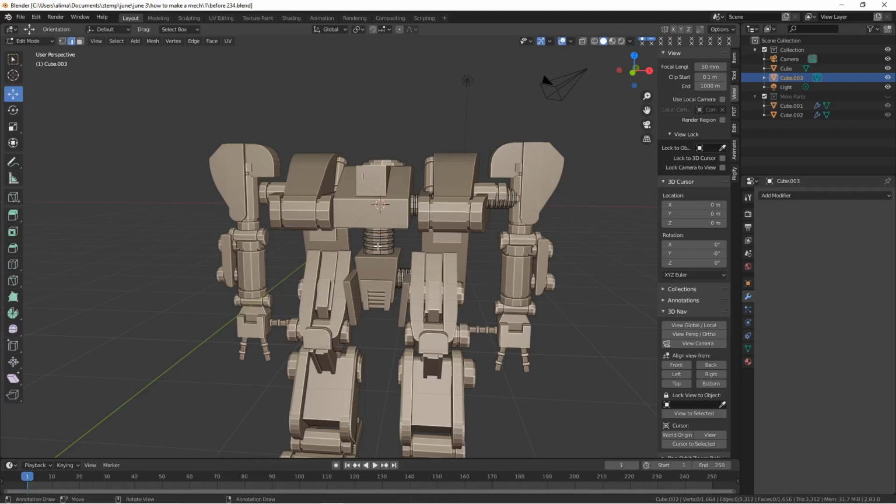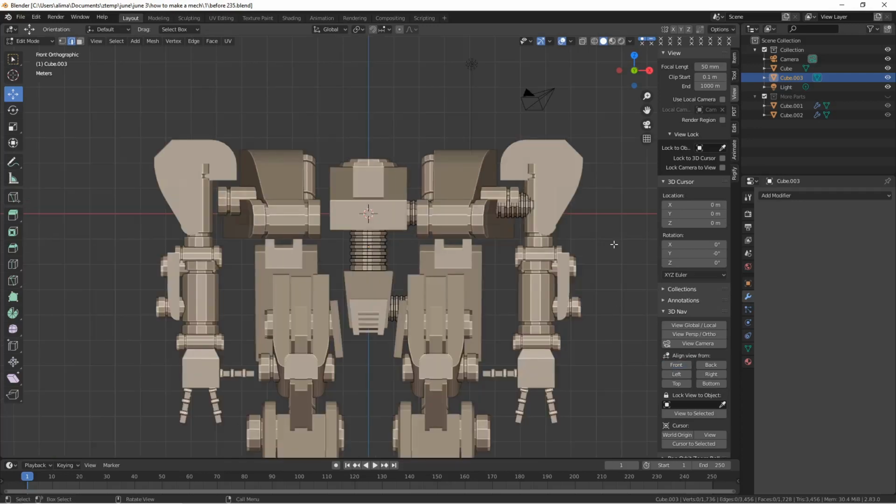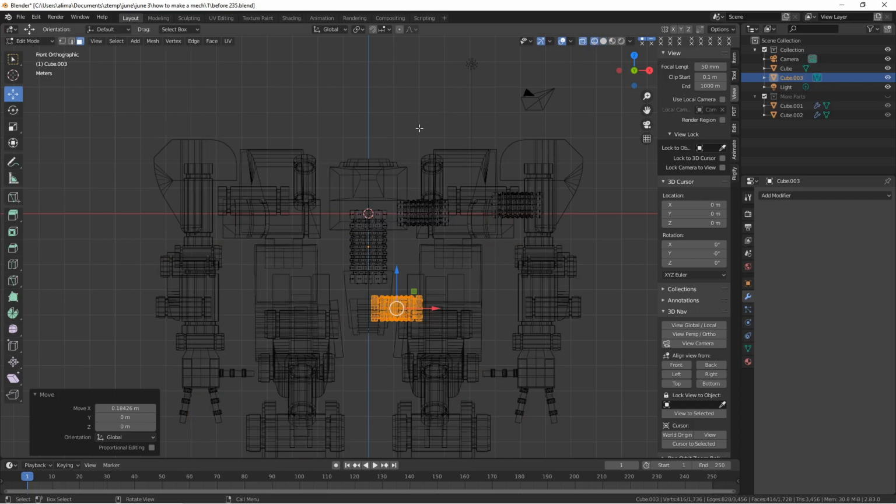Okay, I'll hover here, I'll hold Control, press R, left click once, left click a second time to lock that in. I'll left click on nothingness to deselect. Okay, I'm going to go to the lower right. I'm going to go to front view. I'm going to go to face select, hover here, press L, move this away from the center line, left click on nothingness to deselect, go to the upper right to wireframe select, left click on nothingness to deselect.